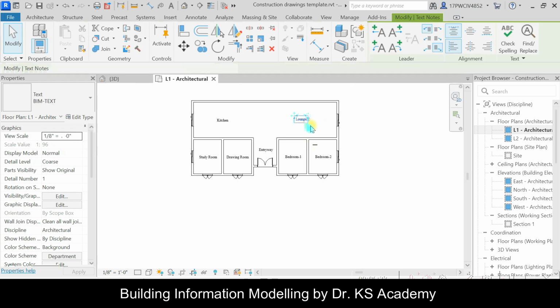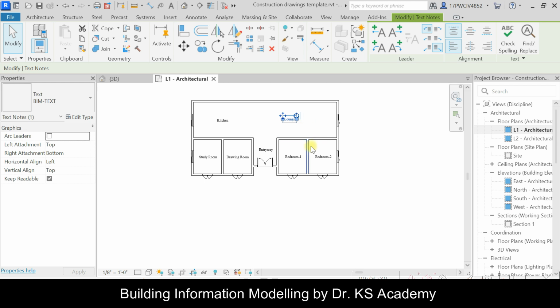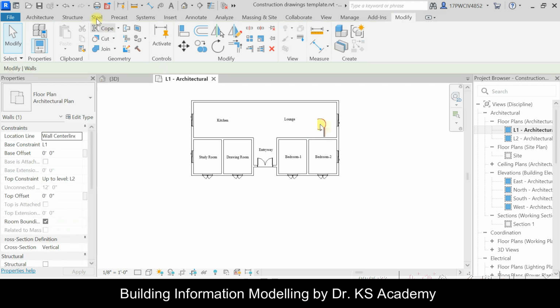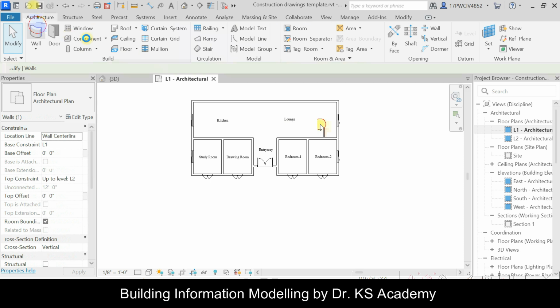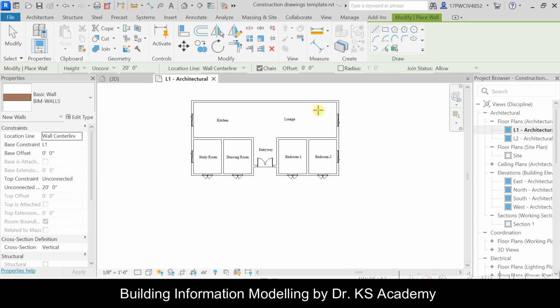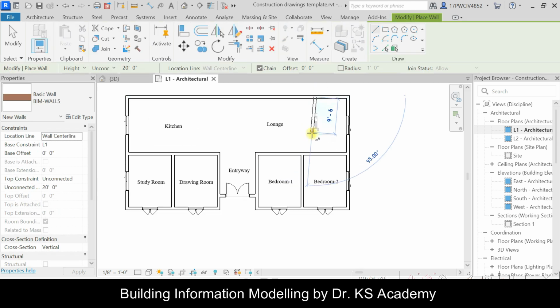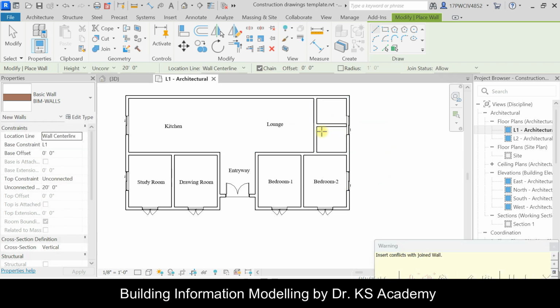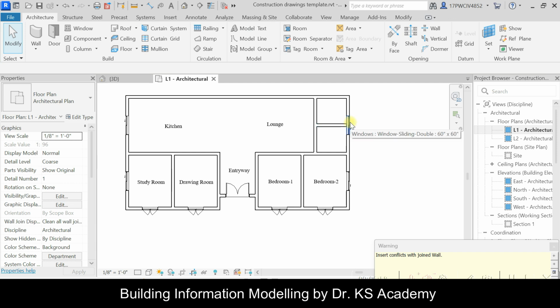From looking at this drawing, we can see that there are no washrooms presently available. So what we can do over here is create an extra wall to locate the washrooms. Now it's asking me to save the project, and we'll wait for a moment, and there you go, it's saved. So let's create 2 bathrooms over here, and let's move it to this point.